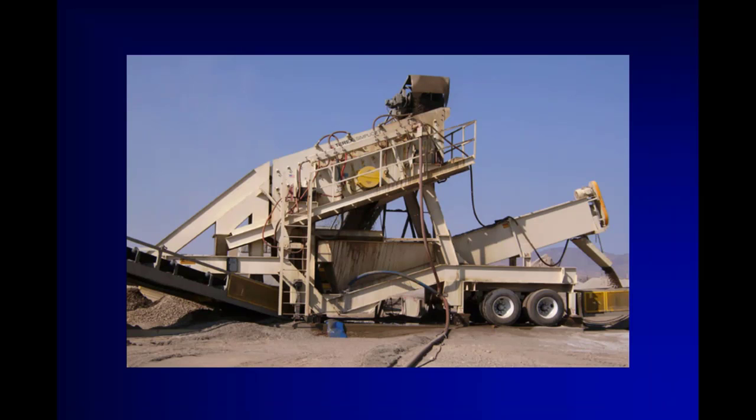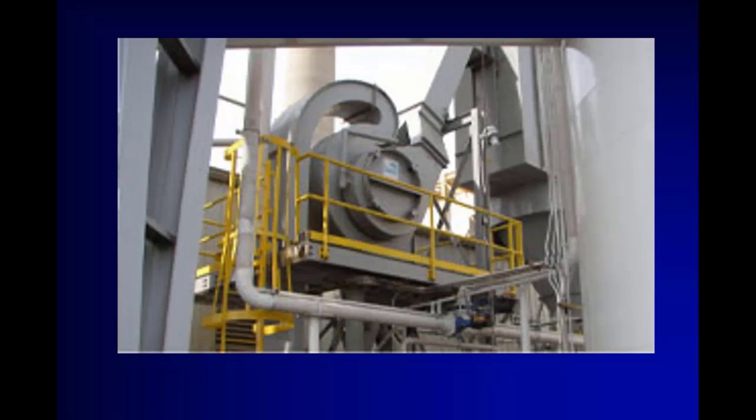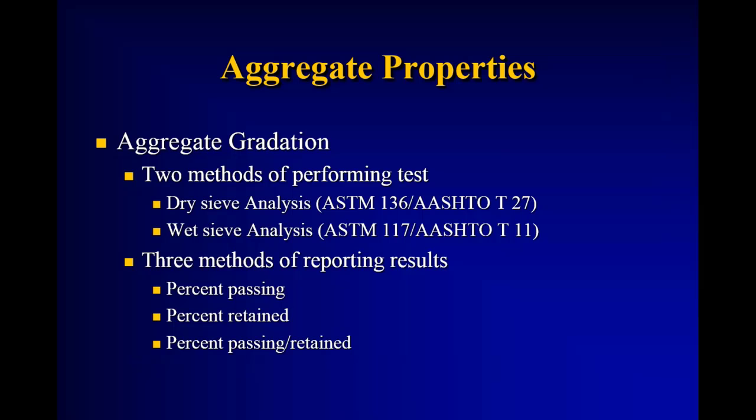So another kind of different type of wash plant. What we see more and more now, in the last 20 years, it's increased greatly, are these air separators, where you cyclone separate the materials with air velocity, basically. Taking the finer materials into a cyclone and removing it and leaving the heavier or higher quality fine aggregate in your live stream.